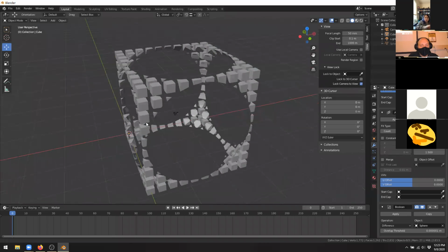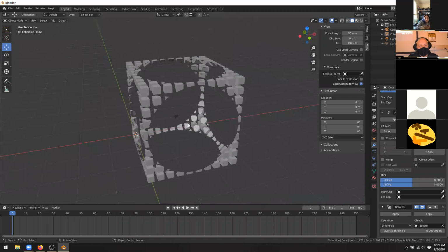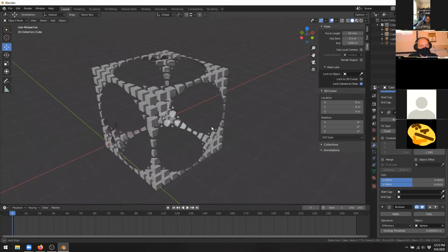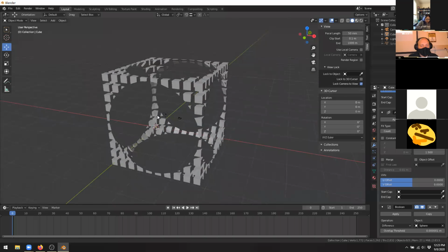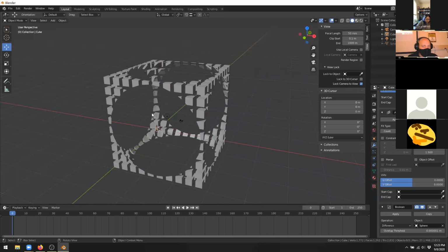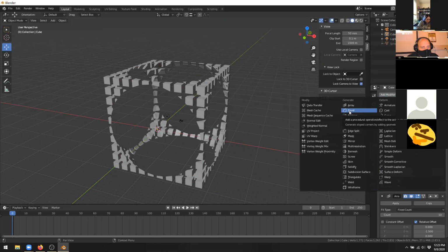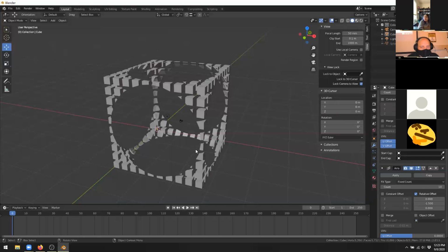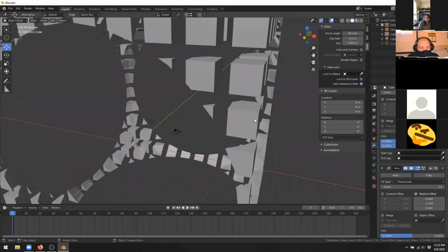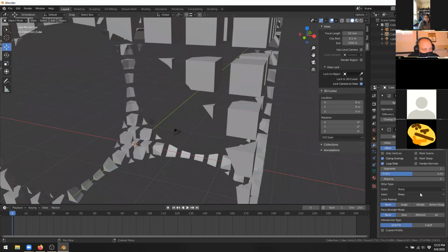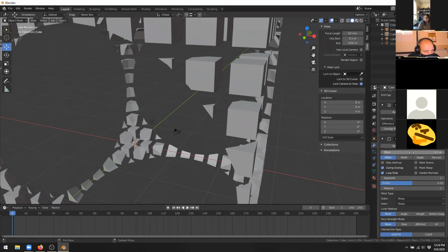Or anything else. And so again, trying to model this by hand, forget it. It would take so long to do and be next to impossible to get it geometrically perfect like this. We're able to do that relatively quickly just by using modifiers to create an interesting effect. And there's a whole bunch of other ones too, right? I can add yet another modifier and choose beveling. And what that should do is apply, let's see, scroll down to it. Where do I want to be with that?